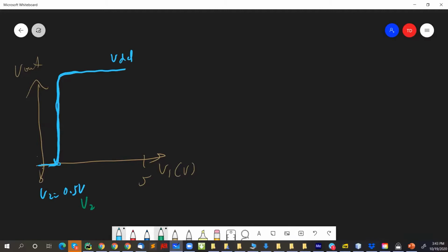But then the interesting bit is when you start increasing V2. Let me take a different color for this next thing. Here I'm going to set V2 equal to 1 volt. And here you hope that it would go like this. So this will maybe be at 1 volt, then I go boom. Ah, man. I quickly jump to here. But it turns out you don't actually. If you look at the set of curves here, you see there's this thing here, and then it kind of slews up. Then it hits this high gain region, and then it slams all the way to VDD.